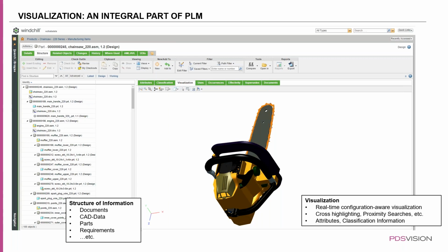As you can see on this image shown here, this is inside of Windchill. So inside of Windchill, you're able to see the visualization because Creo View is embedded in there, and you're able to interact with the model itself. You are also able to export the bill of materials from here. Okay. You can also do things like proximity searches, so you can specify that you want to search around a specific area, and as soon as you search in that area, it also highlights it on the structure as well.